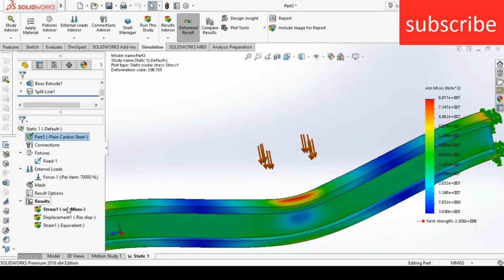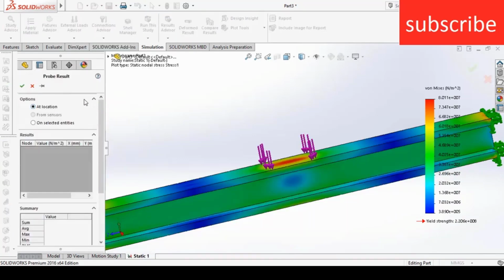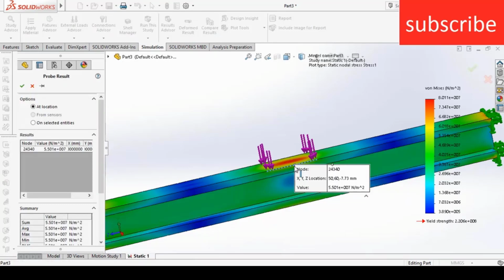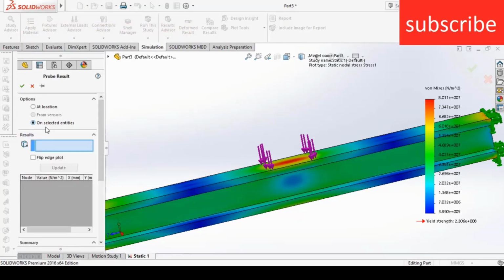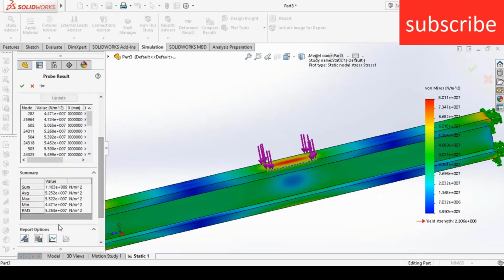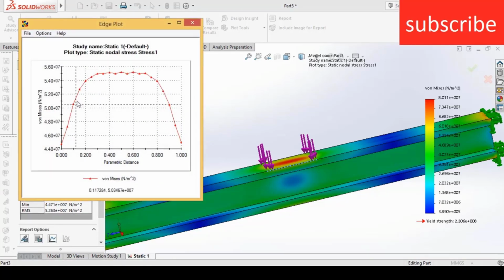Now let me show you another thing. Right click on it, click on probe, select this line. Okay, I'm selecting this edge, click on graph. On select, make sure you click on selected entities. Sorry for the mistake. Now select this line, click update. Now click on graph. As you can see, it shows me a clear picture of how my stresses are acting on this line. Remember, this line is just this long, not the whole beam. You can select the whole beam as per your requirement, but I'm just showing this stress.